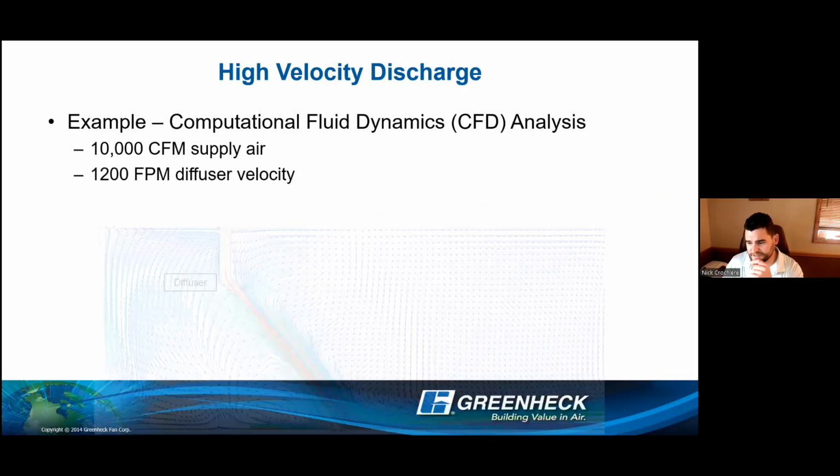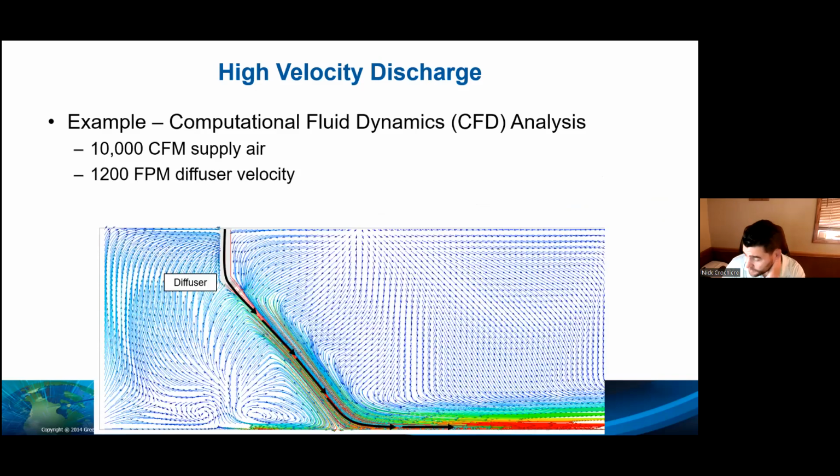Looking at the fluid dynamics here, you can see, again as I just said, that 45-degree elbow, three-way diffuser, blasting down into the space and across the floor. If you're looking where it says diffuser there, that would potentially be the wall if you had a lot of dock doors, and we are going to get into that more. What it's showing is you're moving the air down across the floor, trying to get the greatest throw, and then eventually it will come back up.